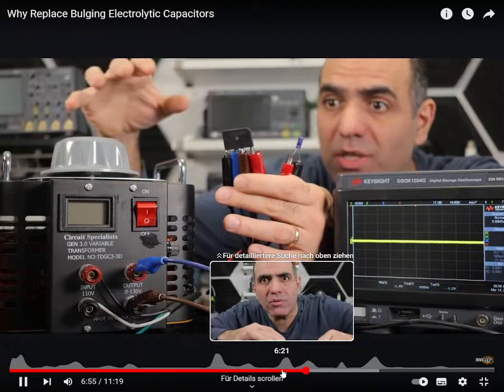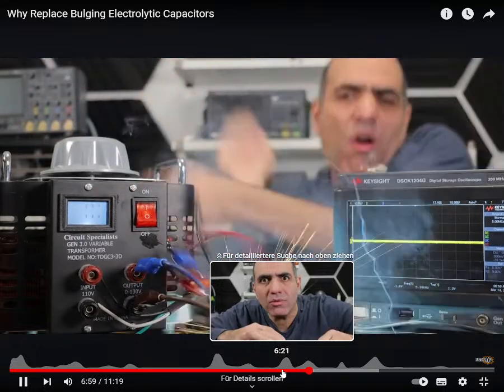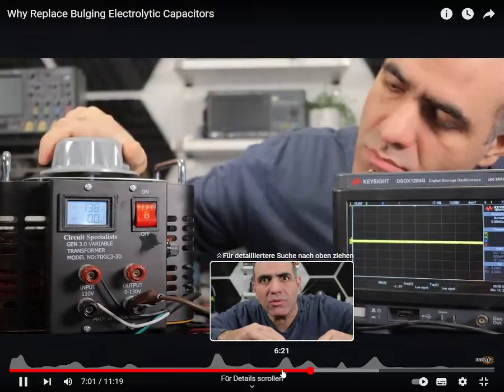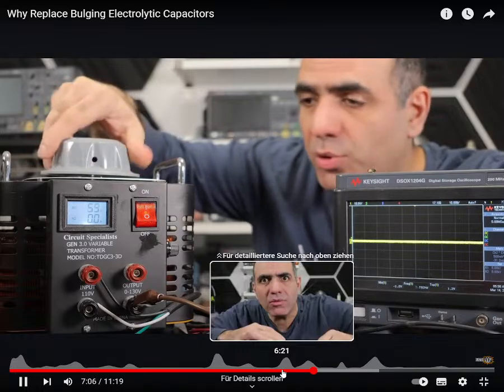Here I have a full bridge rectifier with its output hooked to a capacitor and powered from an auto transformer, so we can provide a safe lower AC voltage. We just have to always reduce your supply's voltage before hooking your circuit up to it.